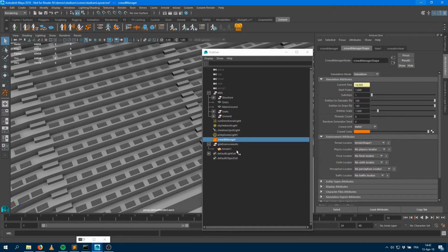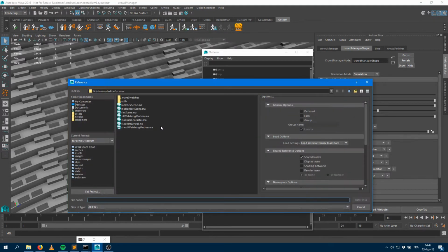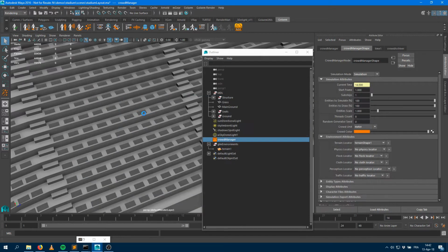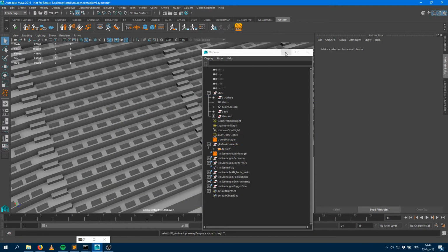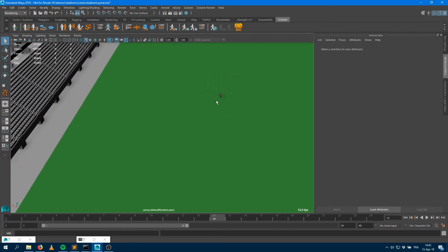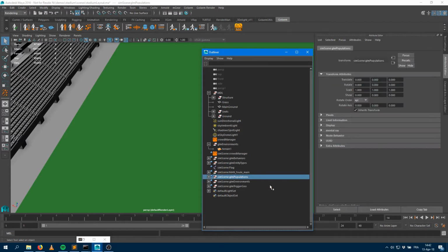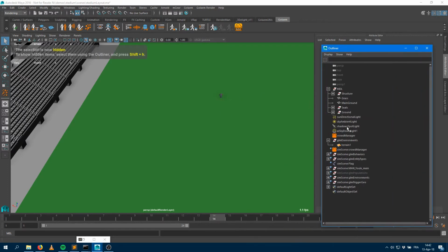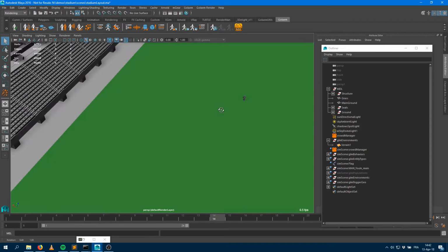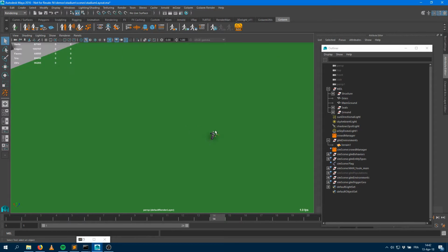Okay, I've created my terrain. Now I can go within Golaem and say create reference, so I can load my simulation scene. It's going to load everything within my scene here. If I take a look at the origin of the scene, I'll get my particles, population tools, and so on. I'm just going to hide these because I don't need them. It's not mandatory, but it's easier for me to figure out what's wrong if I have to debug later. It has also imported my shading holder file.